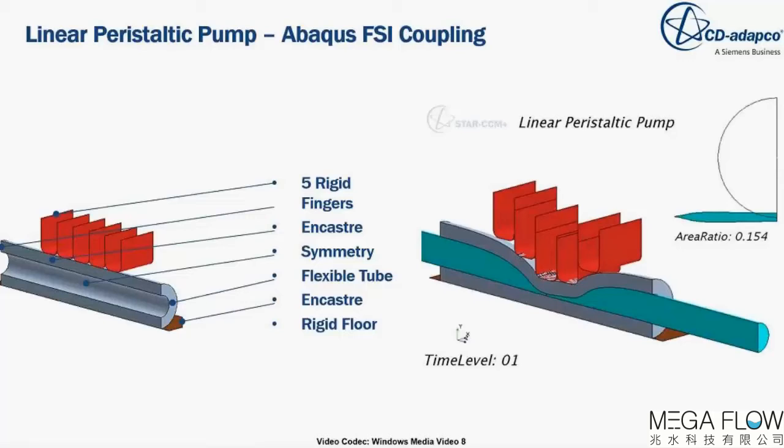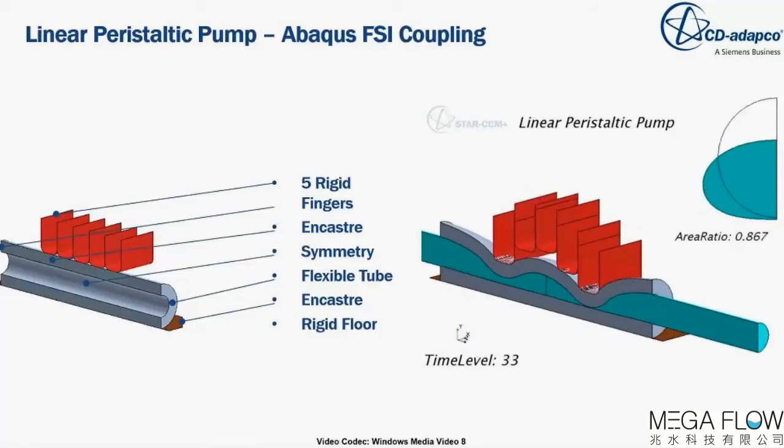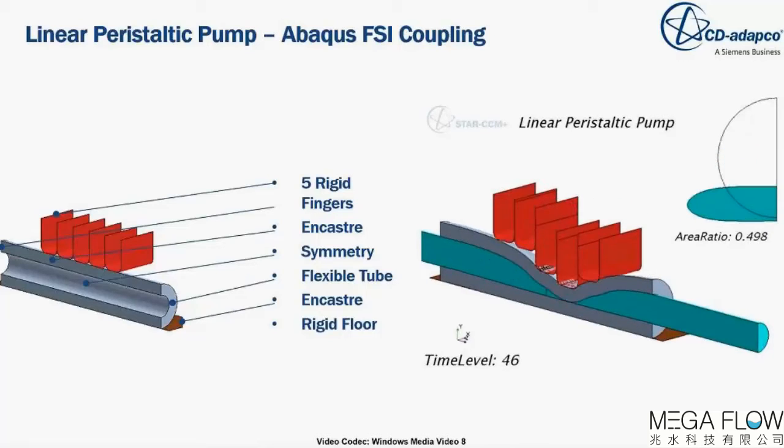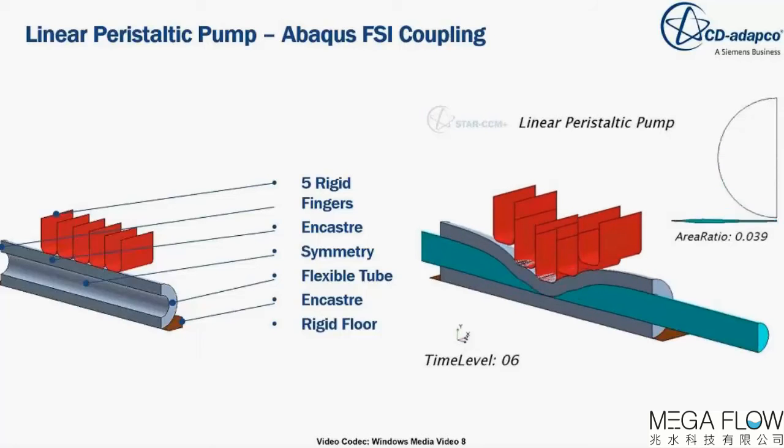As you might know, we couple with various FEA codes to do effective FSI coupling. One of our best coupling methods is implicit coupling with Abaqus FSI. As you can see in this model of a linear peristaltic pump, a very challenging problem where it comes down to almost zero gap with remeshing in this case, and nonlinear behavior of this peristaltic pump coupled with CFD. We also, of course, have our own FEA solver coupled with many others, but we keep supporting and really pushing the Abaqus FSI coupling as one of the strongest solutions that we can see in the industry.